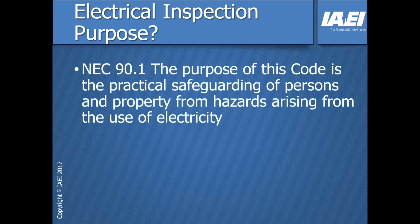And I always start with the very beginning of the National Electrical Code, 90.1. The purpose of this code is the practical safeguarding of persons and property from hazards arising from the use of electricity. So what are those hazards? Well, they're pretty well known and defined in the industry. Shock, and that's where the electricity somehow gets out of the conductors and equipment and goes through you instead of through them. And fire, and that usually results from too much current flow. So basically, those are the hazards.